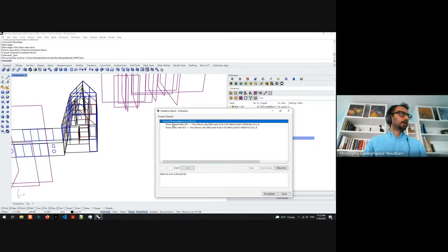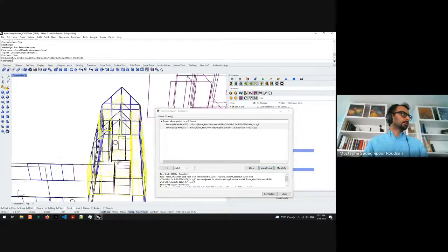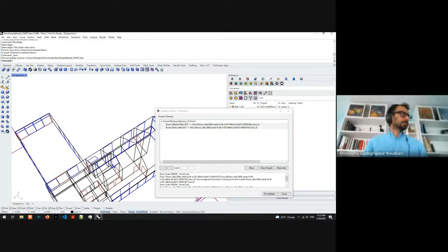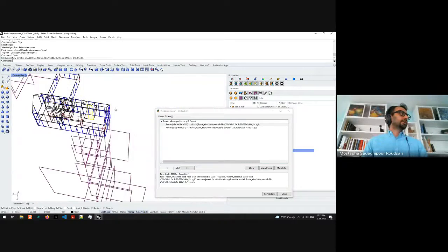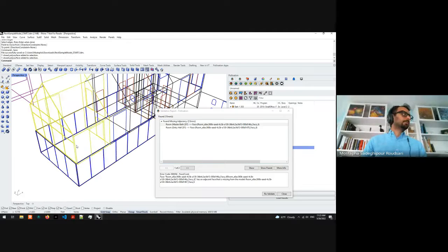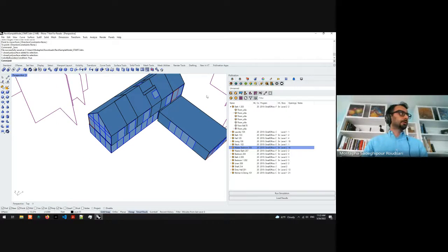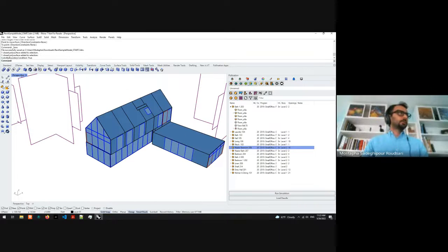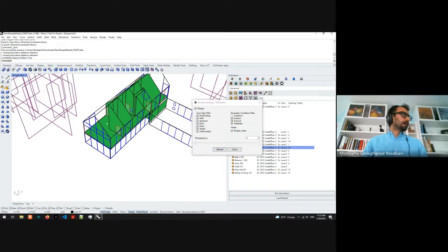Now I have another one here for missing adjacencies. It's telling me there are two faces with missing adjacencies. So let's watch. It's happening between these two. And if I click this one and press show, oh, this is happening here. Why is it happening here? Do you remember I rebuilt this? And when I rebuilt this, it removed all the boundary conditions. How can I visualize this and make sure this is happening? There is a feature here, color by boundary condition. Now everything is blue, which means it's outdoor. Then I can go here and filter by boundary condition. So I can say, don't show the outdoor ones, and refresh this. Now you see what's happening.